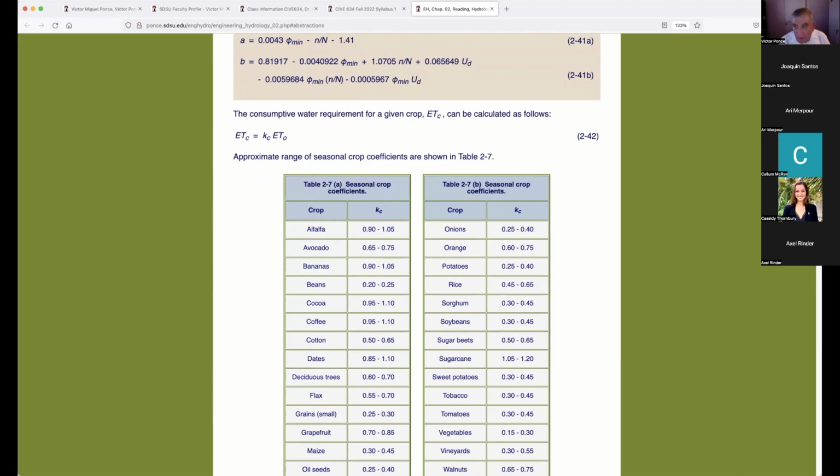Every amount of water, no matter where you get it, has a certain amount of salt. And the evapotranspiration process is going to take care of the water. It's going to evaporate the water, but it's going to leave the salt behind. So you're going to have to provide extra water, not for the plant's benefit, but rather to drain the water by gravity. The drainage has to be by gravity. There's got to be a gradient for moving the water out. And that's what we call drainage. And in the real world, irrigation is always together or coupled with drainage.